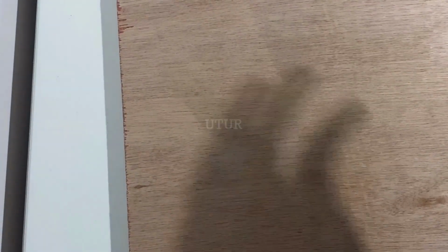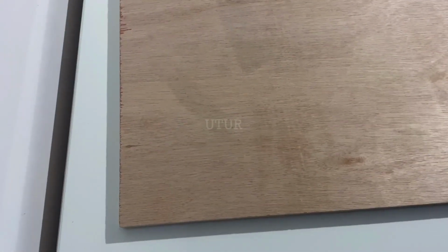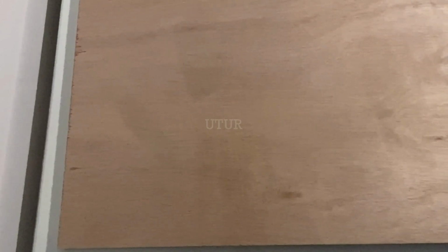Suffice to say, when you're dealing with your plywood, the grain isn't homogeneous or uniform along the grain of the wood and across the grain of the wood, as there is a crossover of ripped grains and cross-cut grains. So using a dedicated rip blade or a cross-cut blade would not be the optimum solution to get quality cuts.